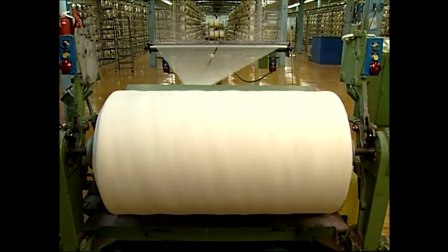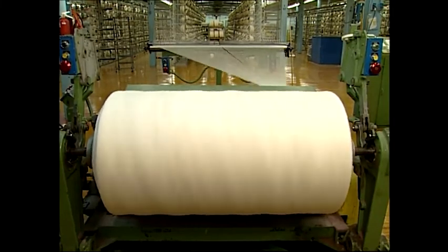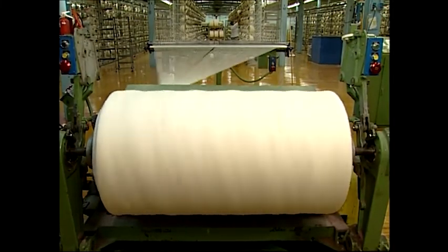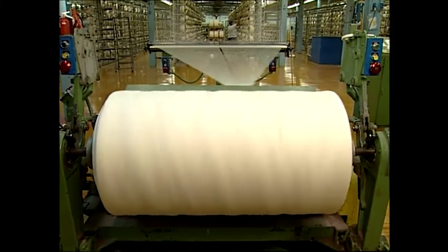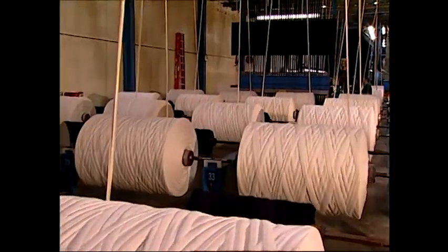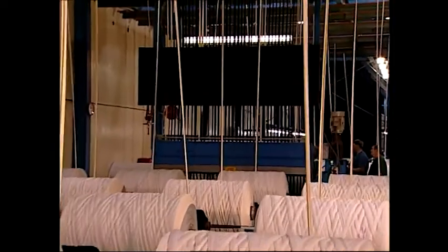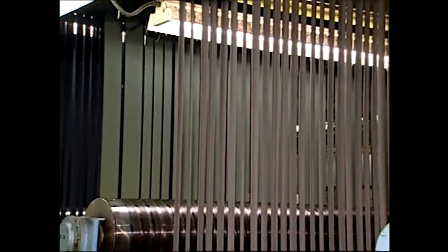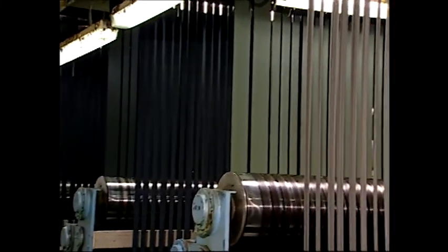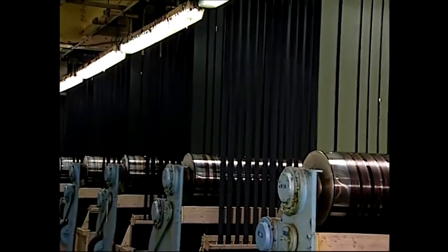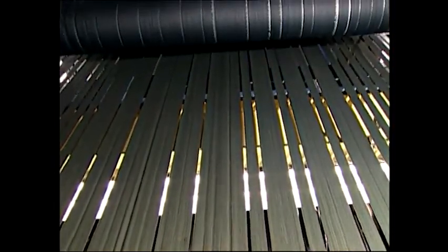By traversing the rope back and forth across the face of the ball, the package is built evenly with constant tension. The ball warps can be from 500 to 25,000 yards in length. They are added together behind the rope dyeing range in a magazine creel to form a die set. The die set is always a multiple of the number of beams in the slasher set. For example, if there are 12 beams in the slasher set, there will be 12, 24, or 36 balls in a die set. The yarn is then unwound from the balls and is passed through the dye range.